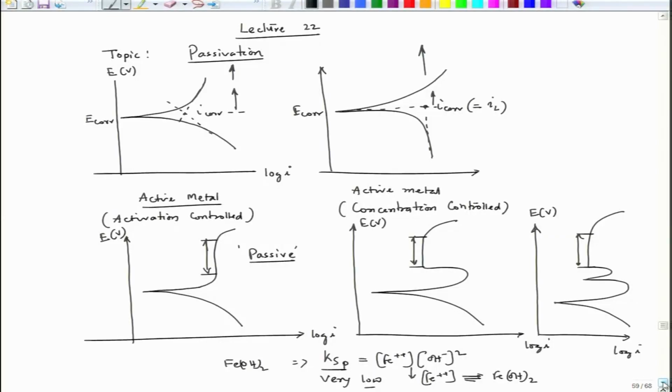Okay. So, now when you talk about passivation, we always refer to this kind of graph, and of course, this particular graph is a typical graph which confuses us as to whether the metal is attaining passivity or not. We will talk about the origin of why this graph appears. We call this particular segment unstable passivation, and these two are forming the stable passive state. This particular segment is spontaneously passivating.